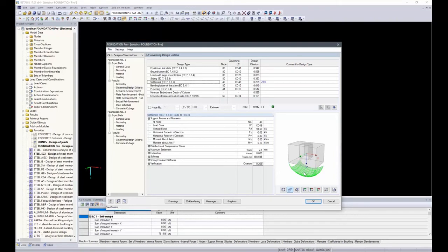This looks like the module is calculating using a flexible foundation slab, but if you see this message 211, this means the calculated plate stiffness is greater than 1.0, the plate is solid.